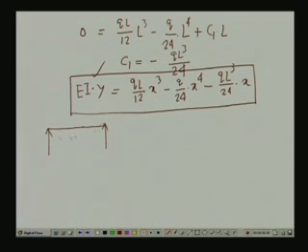Now, since this particular beam is symmetrically loaded with a uniformly distributed load, it is expected that we will have the maximum deformation at the center. Now, if we compute the value of the deflection at the center, that means y at x equals L by 2, let us see what we get as the value of y.